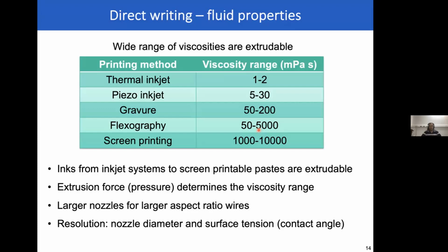Okay, so how are you growing the base? Is that also spin coated, or are you buying the substrate? Sir, first the base I'm depositing by sputtering. The top and base are sputtered zinc oxide metal oxide films, in which silver nanowire commercial ink is embedded as spin coated thin films. Okay. So as I said, with pure silver nanowires, we do find the adhesion to be an issue.